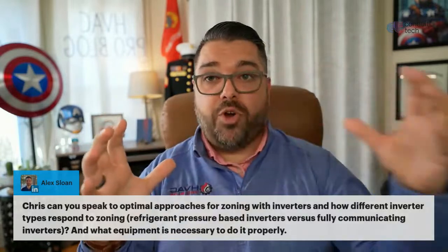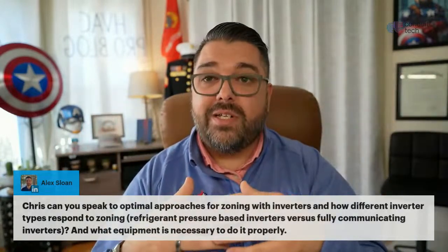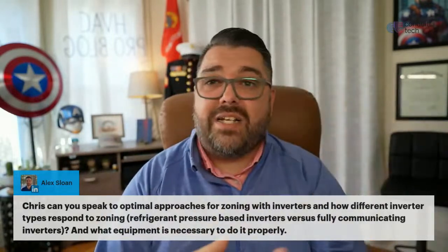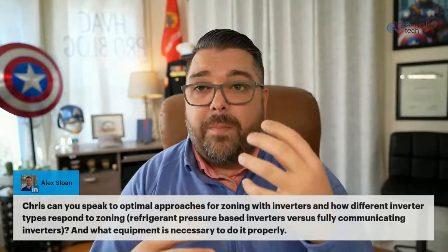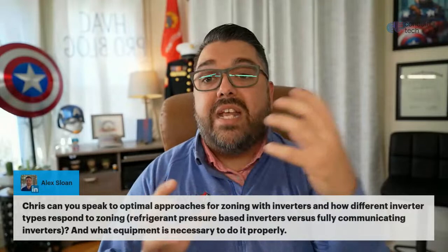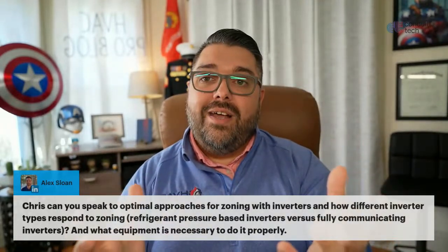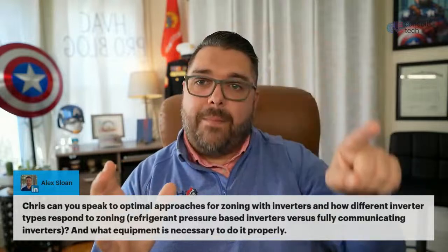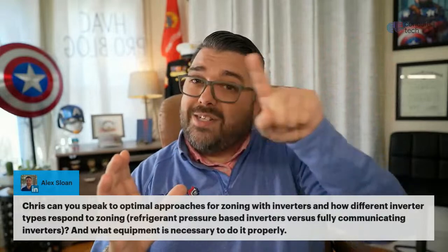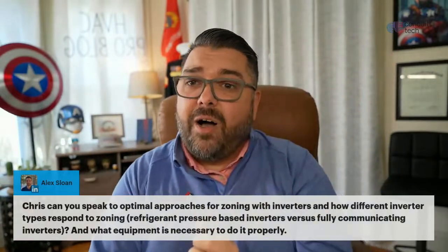If we try to use a third party that cannot communicate, so the basic open close dampers, that's where we start running into problems, and we start putting in things like bypass ducts and ways of addressing the higher static pressure and the inefficiency of doing that. And then it becomes a race, right? When we start running bypass air across a furnace, does it reach temperature in the space or does it short cycle first? Okay. So yeah.